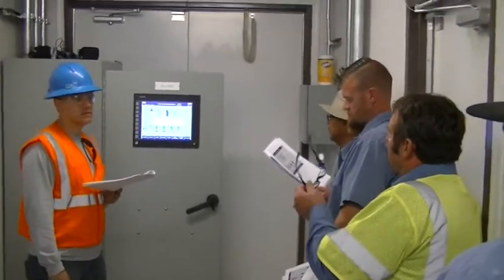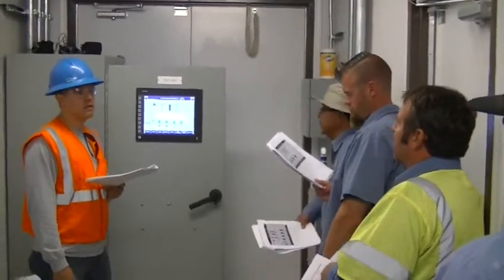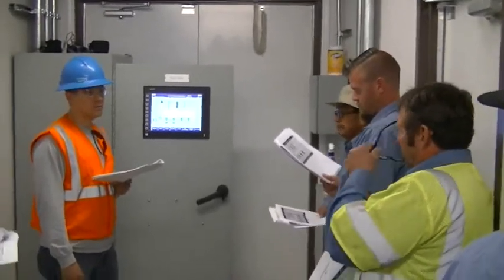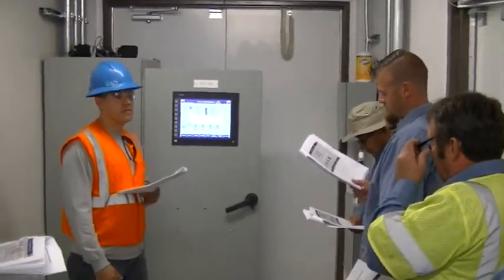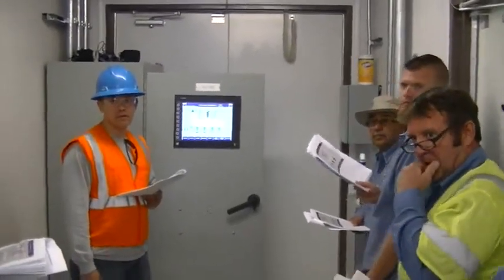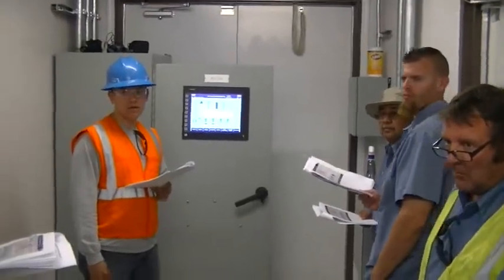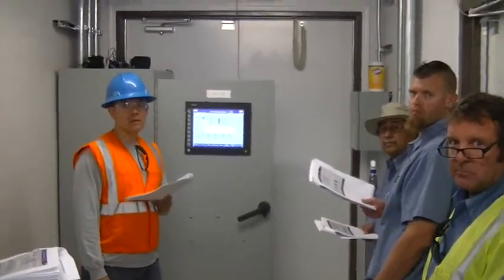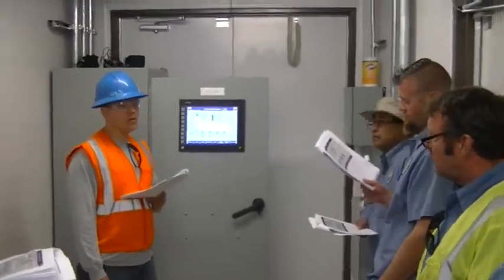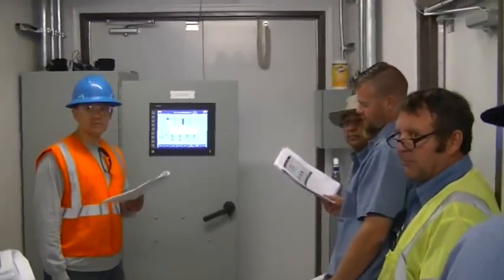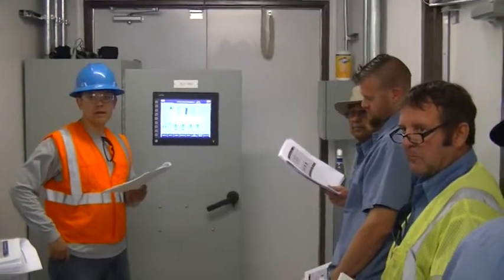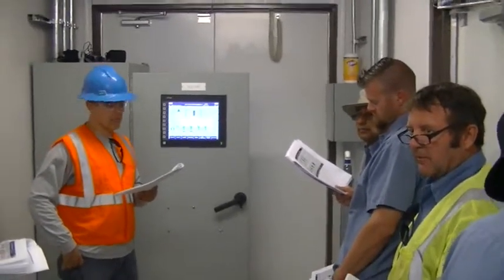Correct, whereas normally it's say 1,500 gallons a minute or something. So it would make you think there's a problem with the pump. What if the shaft broke, or one of the valves out there left shut? Yeah, could be a number of things that would prevent you from reading the flow signal. Or the flow meter itself is having trouble. Yep.